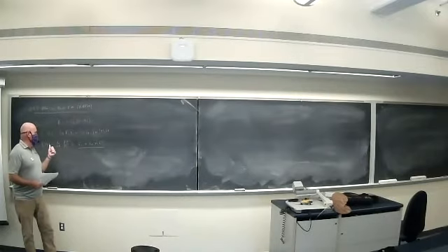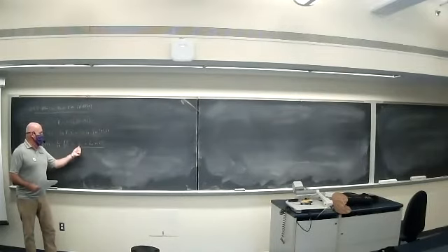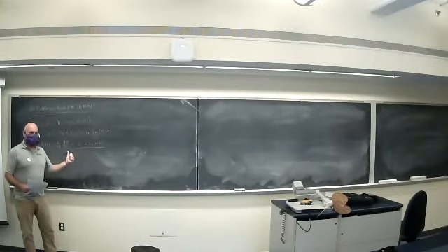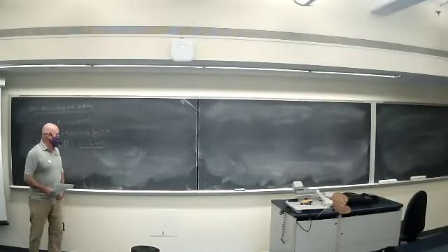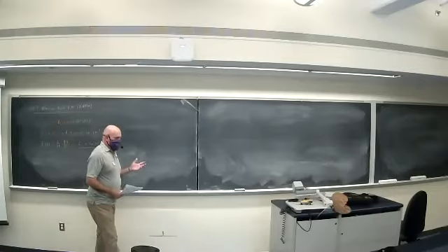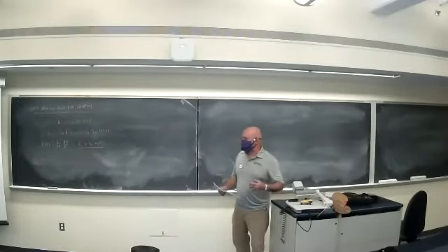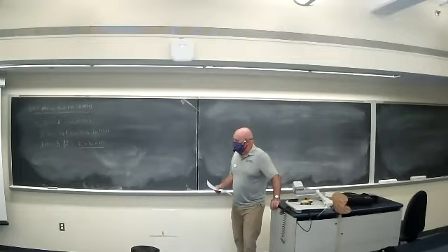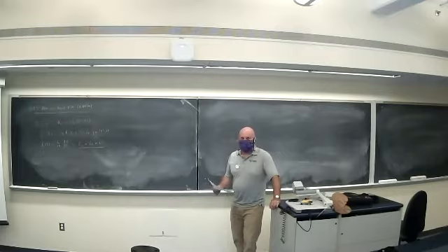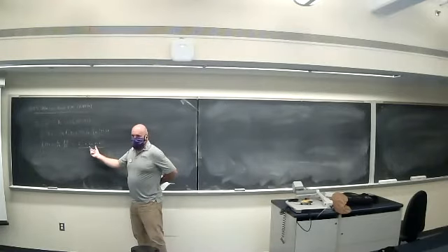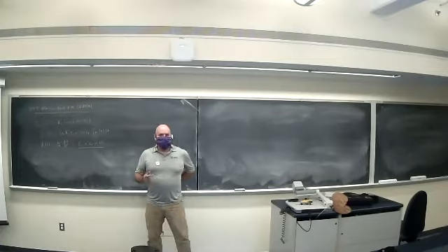That means the instantaneous frequencies would go to f_c plus k_f as the highest frequency, and f_c minus k_f as the lowest frequency. So at first glance, you might think that means it has a bandwidth that's just 2 k_f, right? Because that's the range of instantaneous frequencies. And so by making k_f small, I can get a really small bandwidth.